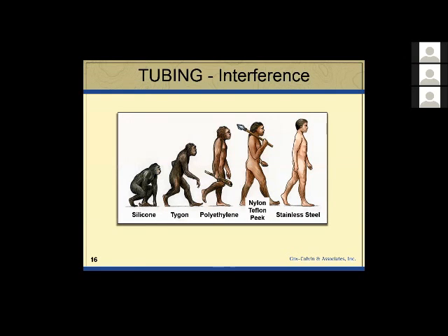I personally like nylon. Now there are a lot of studies, including Greg Ouellette, who has often shown a figure of his. It's a graph where he sent hydrocarbons through 50 feet of tubing. And when the hydrocarbons got to the end of the 50 feet of the Tygon tubing, for example, there wasn't much left. He lost about 90% of his compounds. Teflon showed up as best, nylon fairly close.